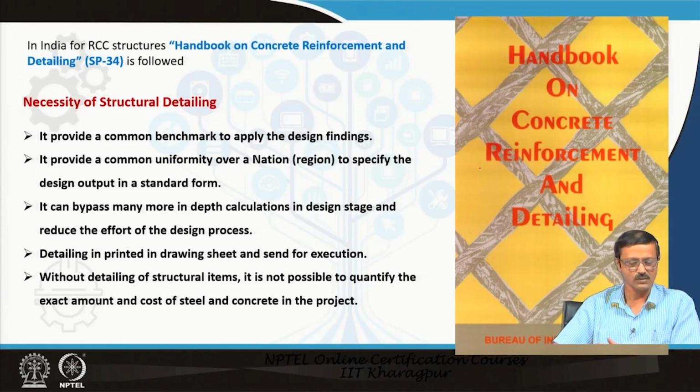The last but not the least, without detailing of structural items, it is not possible to quantify the exact amount and cost of the steel and concrete on the project. Yes, because as you know, the project cost and the project estimation are based on the final design diagrams and working drawings for the non-structural elements, and for the structural elements, the structural detailing sheets.